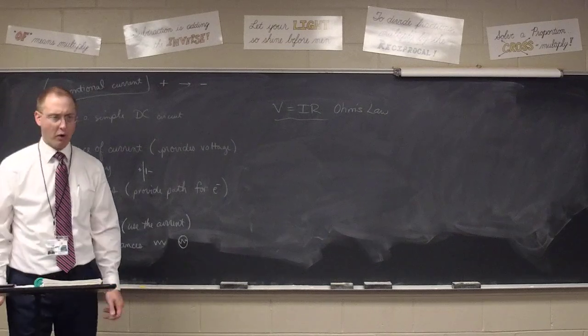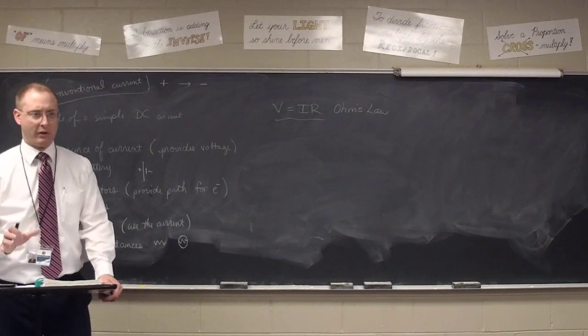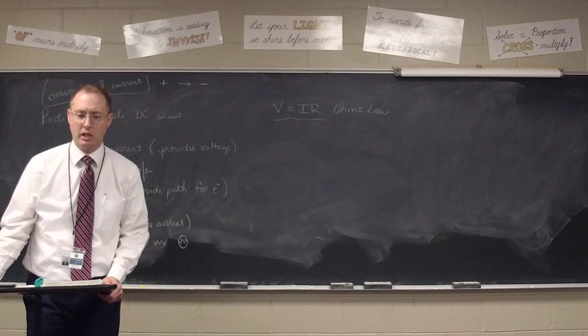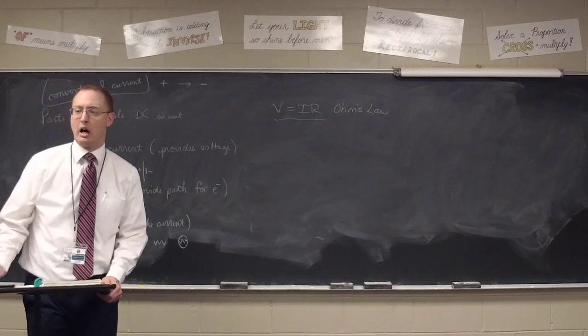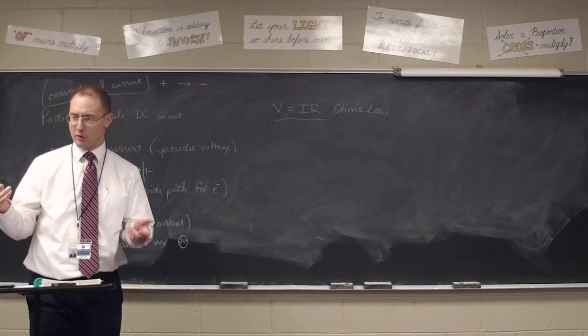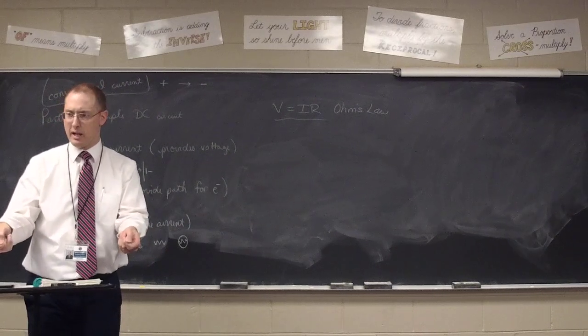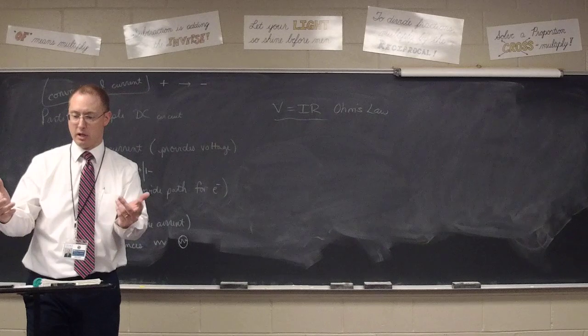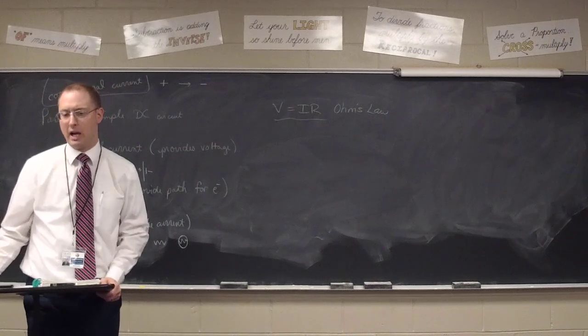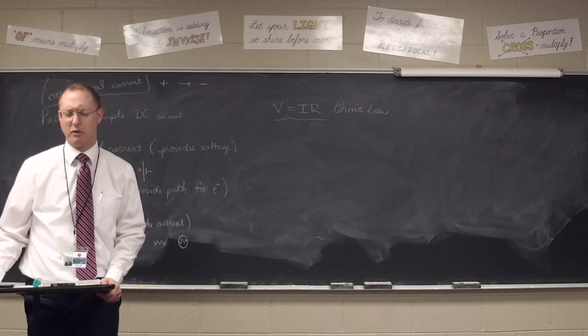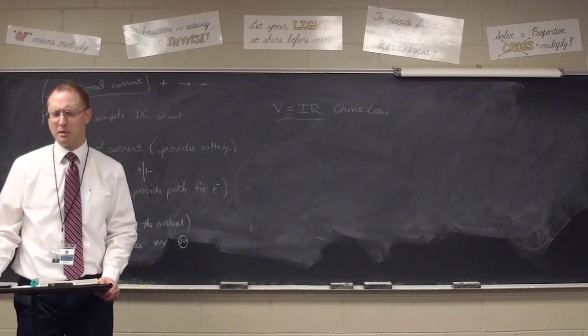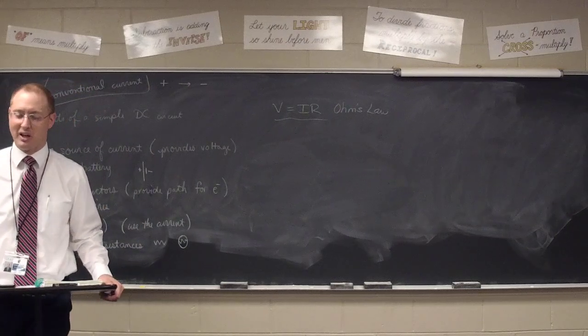All right, so 12 volts, by the way, is a typical automobile battery, somewhere between 12 and 13 volts. So if you're ever curious how your battery is doing, you can take your voltmeter, touch the connectors to the terminals, and have somebody crank up the engine and see what your voltage does. I had to do that recently because my car was starting to have a few little issues starting. Not bad, but it makes me nervous. I don't want to be stuck out there somewhere.